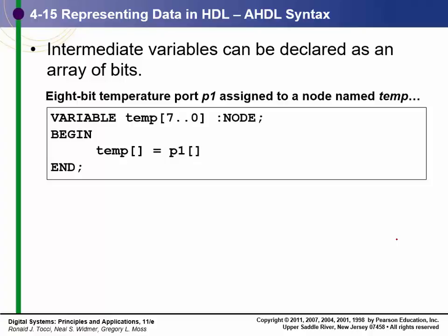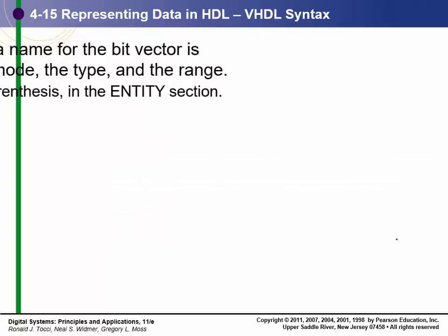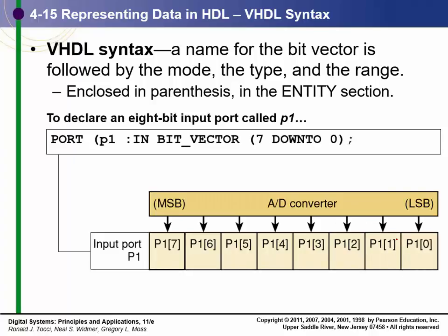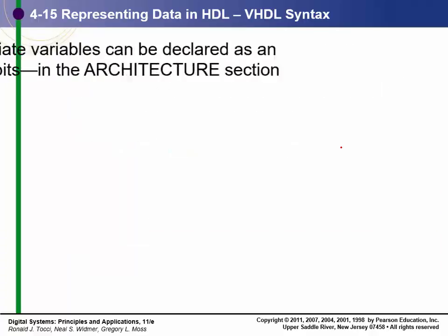This is how you would define an input port in VHDL. It's a bit vector, 7 down to 0, then it's an 8-bit port.